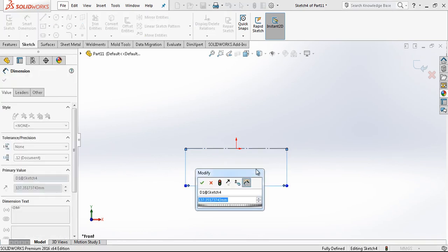Because I started so many years ago by drawing this kind of technical drawing by hand, it was the rule to always use a center line. This is a habit. Also, you can use these center lines in your drawings also. That's quite useful. For that reason, I recommend you use construction lines as soon as possible.